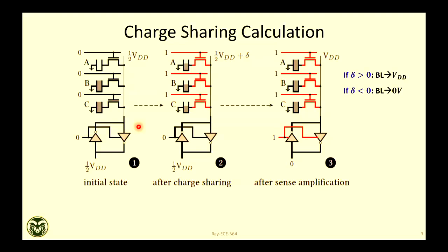So let's see how we will do this. This is your general philosophy that we read. We also did it for normal sensing. When you do normal DRAM sensing or single row sensing, we started with this criterion because charge is conserved. Charge is a conserved quantity. So before sensing, whatever your initial charge was, after sensing, the total charge will be the same. So this is your before sensing charge. Charge is on the bitline capacitance, and charge is on the three capacitors. Capacitor charge is Q equal to CV. So cell capacitance times voltage, VDD.